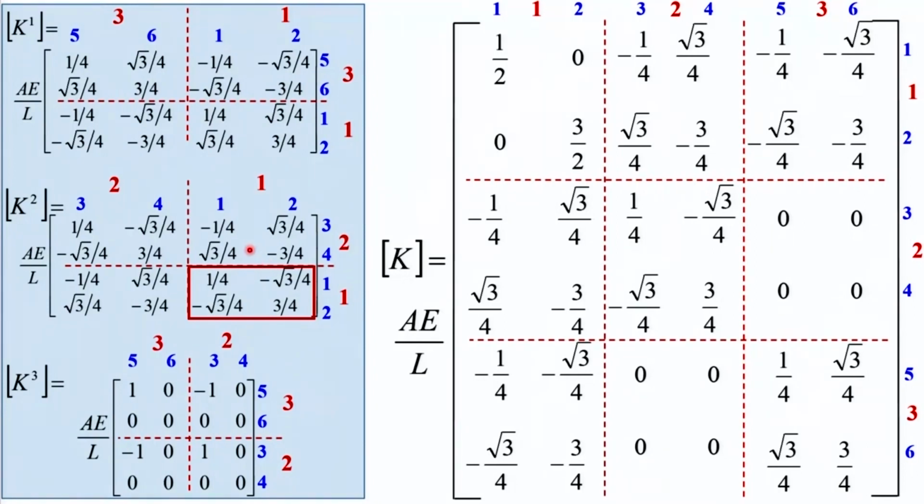Now, let's go to element number 3 then. Element number 3, first we will say 3 and 3. Now, already we have this third node is common between element number 3 and element number 1. So, already this is the contribution from element number 1. Now, the contribution of element number 3 need to be added here. If we add this block to this, this becomes this.